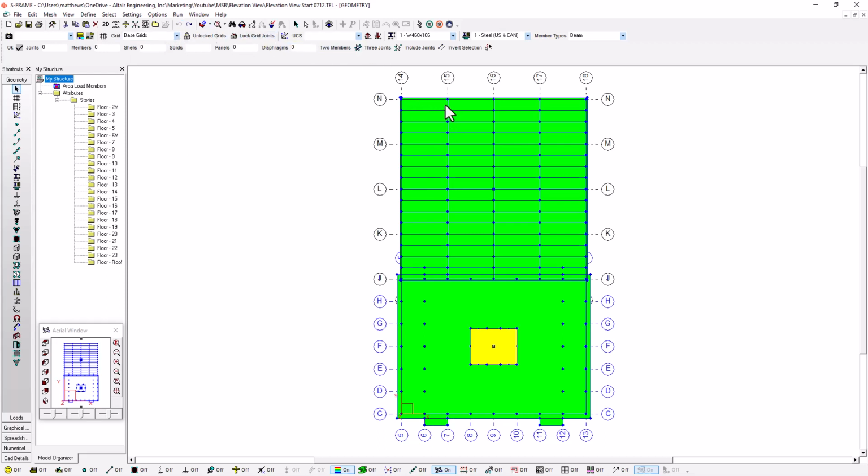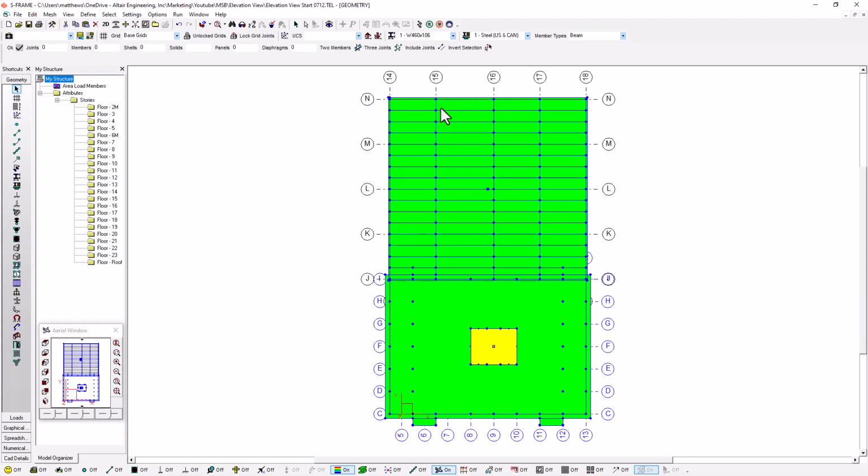And if I wanted to make an additional change and say, rather than adjusting just a plane of geometry, I want to adjust a volume, I can left click on the same grid line 15, but hold down shift before I do so, and left click and drag. And when I do this, notice that not only is the plane of geometry along grid line 15 moving, but the volume on the left side of it in the direction I'm moving.